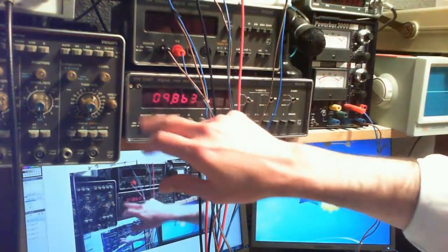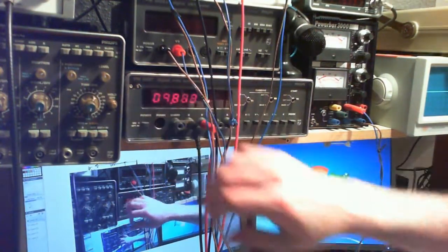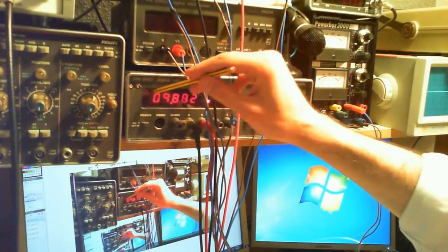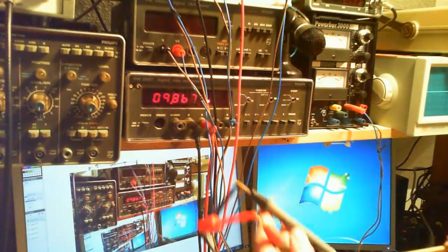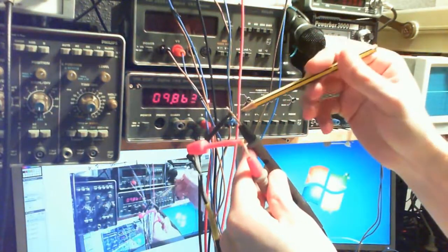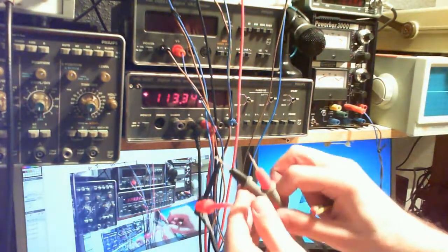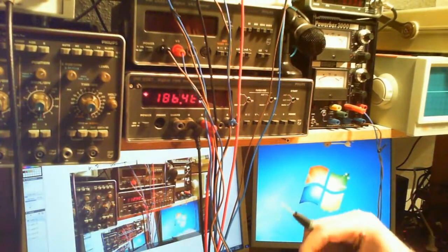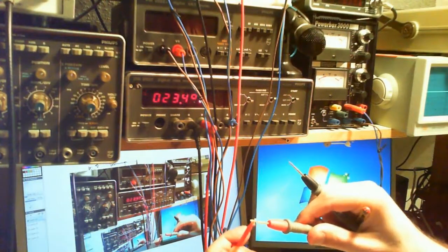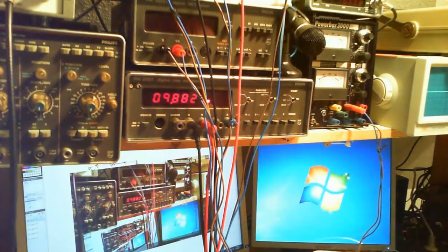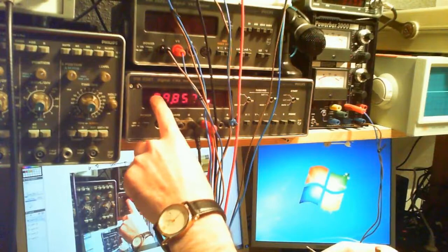But on this multimeter, if you don't have a positive sign over here, that means that you have connected your leads in reverse polarity, meaning that you have connected positive to negative and negative to positive, which is actually not the case. I have connected positive to positive and negative to negative, but it's still showing me some negative voltage.